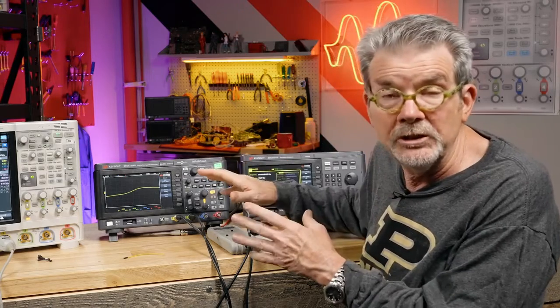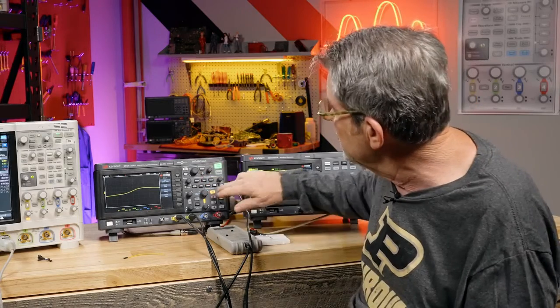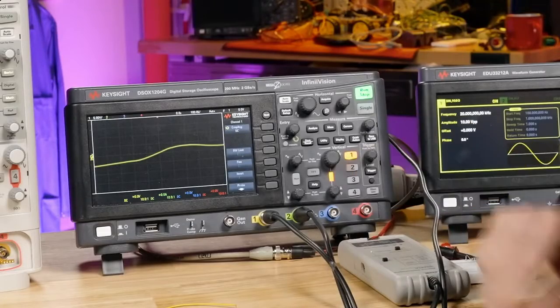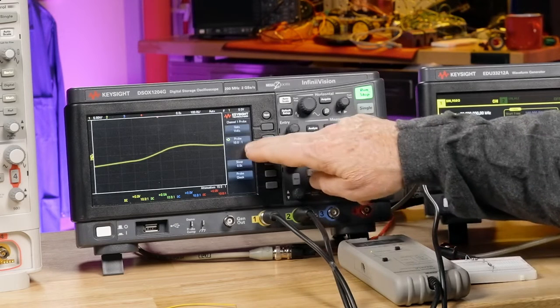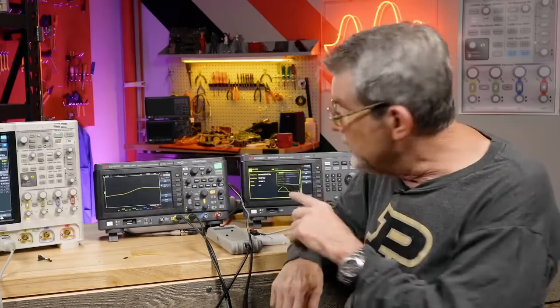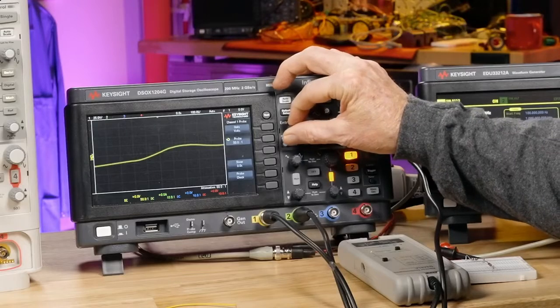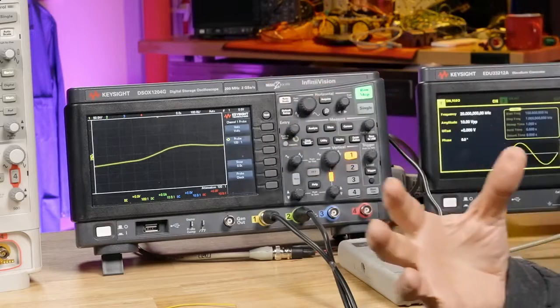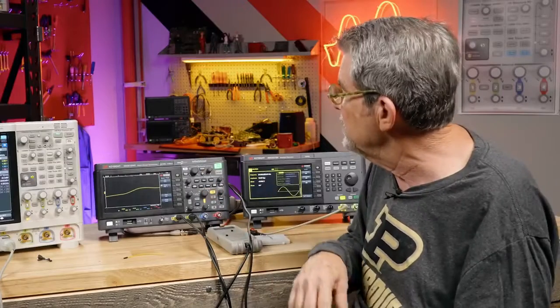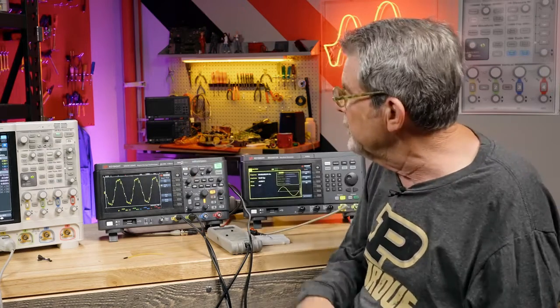is we need to tell the scope what the probe attenuation factor is, or the conversion factor of each of the probes. So I'm going to go into the Channel 1 menu, select probe, and you can see it says 10 to 1. That's where it was set the last time. I've got my high voltage differential probe set to 100 to 1, so I need to change that to 100 to 1 so all the measurements will reflect that level of attenuation. Then just set it up like we've discussed earlier.